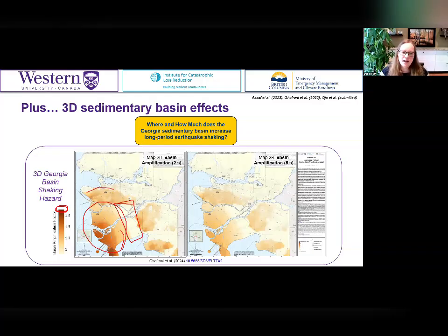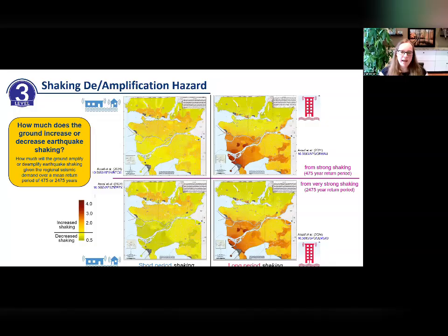But then as you get into the uplands of Vancouver, Surrey, and White Rock, the ground is stiff, and the 1D site amplification doesn't expect how much amplification is happening at long periods because the VS30 is quite high. It doesn't know that it's still sitting inside the Georgia Basin and is experiencing propagation of the higher amplitude surface waves as they propagate out of the deeper part of the basin. So we have to add that into our maps, or into the amplification result.